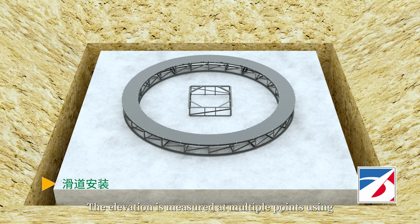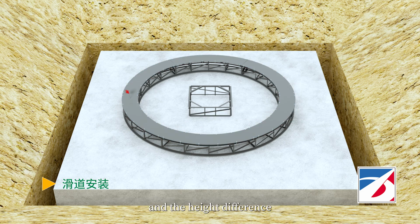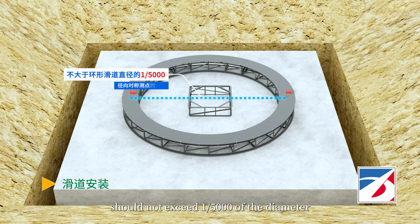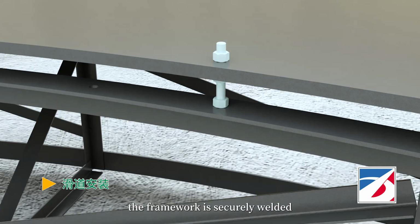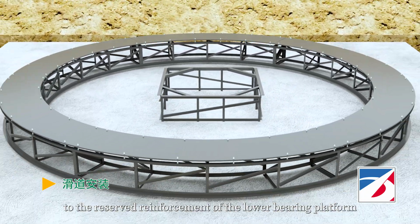The elevation is measured at multiple points using an electronic level gauge, with the requirement that the relative height difference within every 2 meters range should not exceed 1 millimeter, and the height difference between radially symmetrical measuring points should not exceed 1/5000th of the diameter of the circular sliding tracks. The framework is securely welded to the reserved reinforcement of the lower bearing platform.